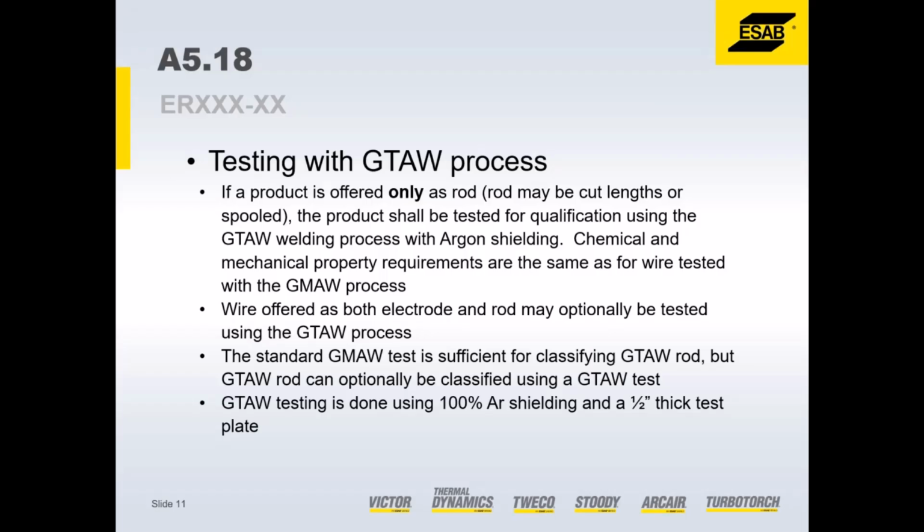So these products are tested with GMAW. They could also be tested as GTAW. If it's only listed as an R, that would be only intended for use as GTAW or TIG welding process. If you're going to have the ER, then it would be available for a gas metal arc welding or MIG welding process.